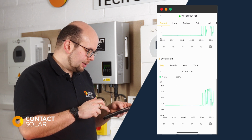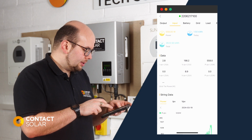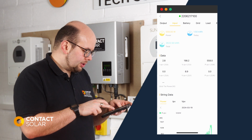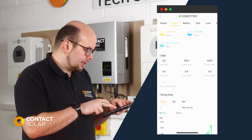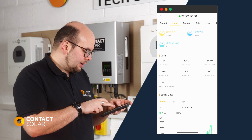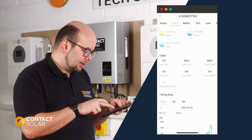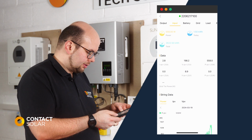On the input section you'll be able to see the solar production. There are two trackers on this inverter, so two DC solar inputs. At the moment on this installation there's only one string connected and we can see the current once again, the voltage 198 volts and the power that it's producing, 558 watts.